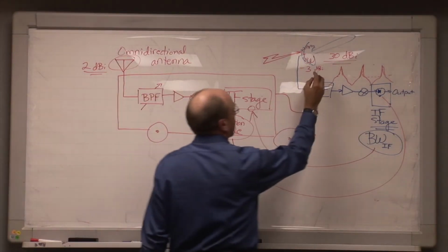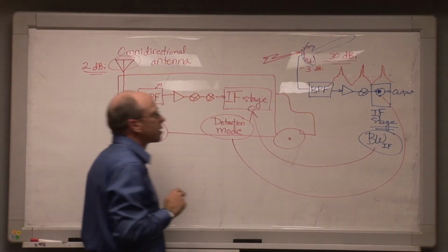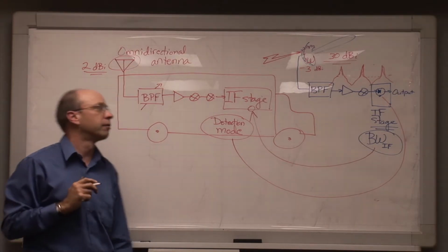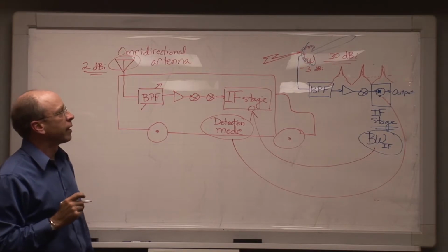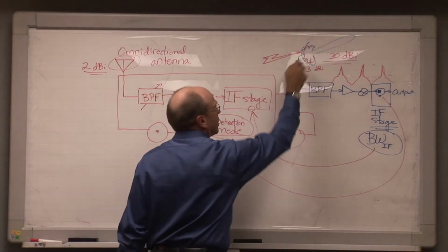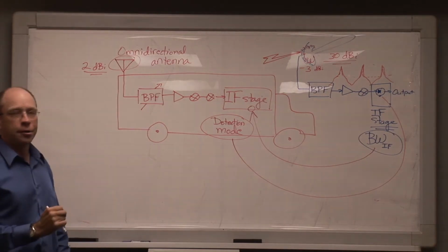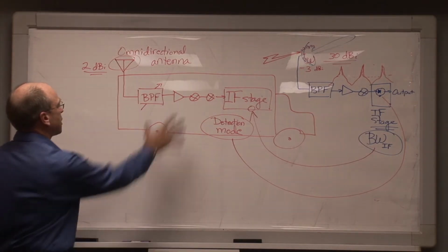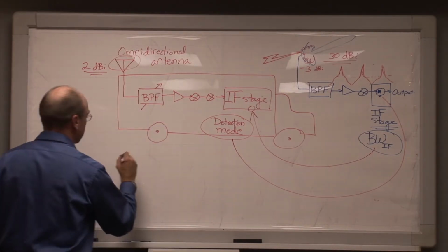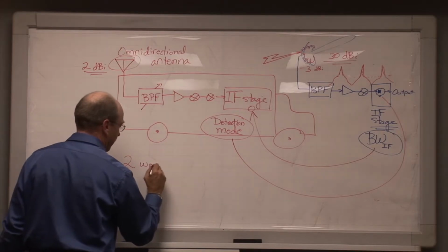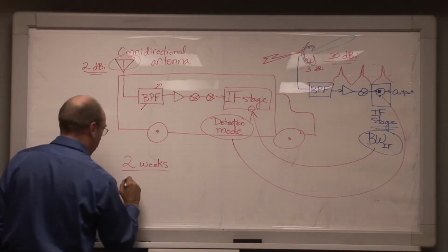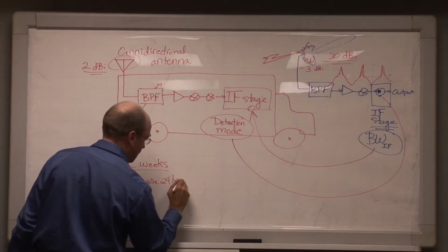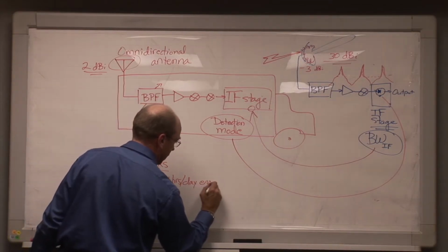This scenario, for example, has occurred where a high-gain antenna that was being used for space communications was inside an electronic warfare range, and there was a suspicion, which was not confirmed, that the people who were performing the electronic warfare activities were inadvertently interfering into this communication link because they were turning on electronic warfare systems that they shouldn't be turning on. Well, that's entirely possible. But this is where our survey comes in, because what we'll do is set up this survey and probably run for about 2 weeks. We'll measure, during that time, 24 hours per day, every day.